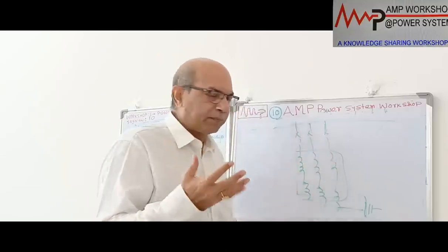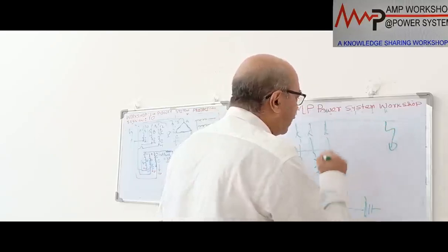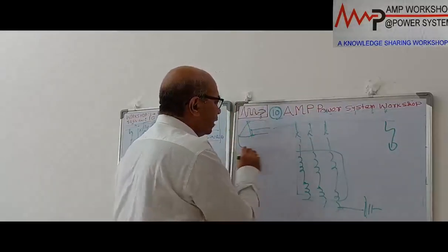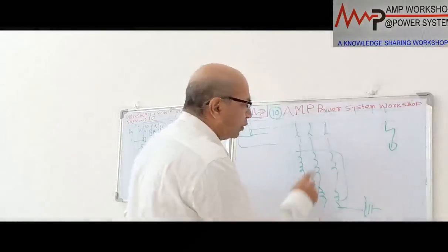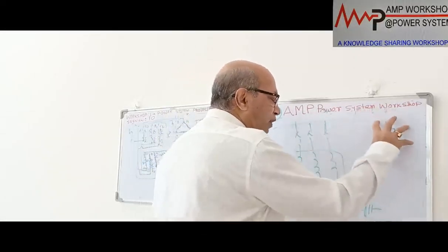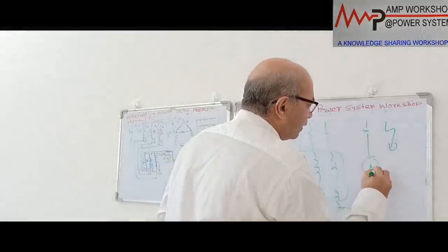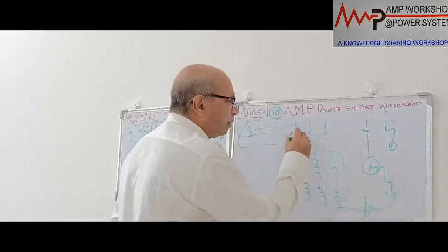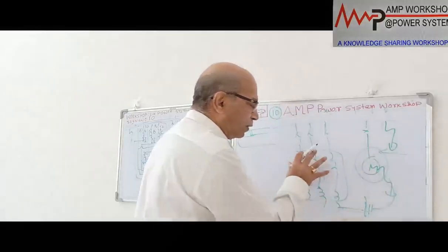So that is the second part, because when there is any earth fault in the 6-point delta connected system, since it is coming from delta, immediately earth fault current will be flowing through this. So this is not the fault of the transformer, this is an external fault. Suppose this is a motor feeder connected over here, and there is an earth fault in the motor. The earth fault current will go through this transformer, flowing this way. In that time, this motor should trip on earth fault, not this transformer.